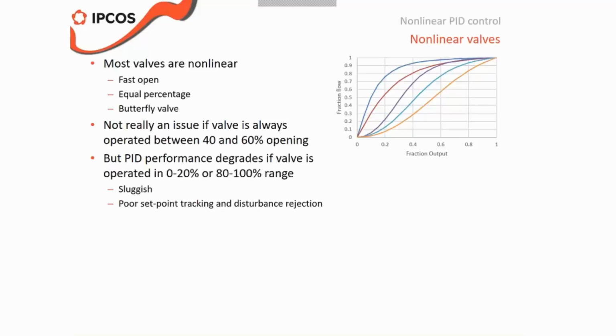But as I said, when we have a swing unit where the load can be anything between 75 and 100%, that probably also means that the valve will move somewhere between, let's say, 50% and 80 or maybe higher percent. And that means that it will move through the entire nonlinear characteristic.